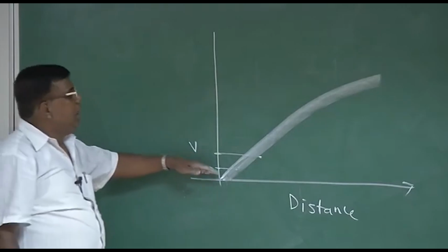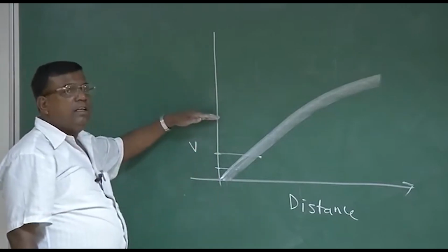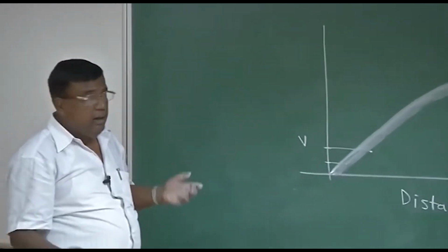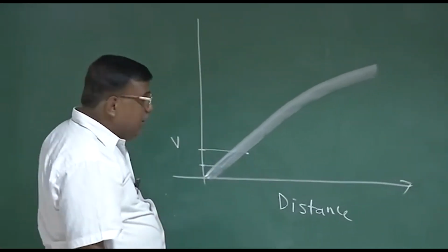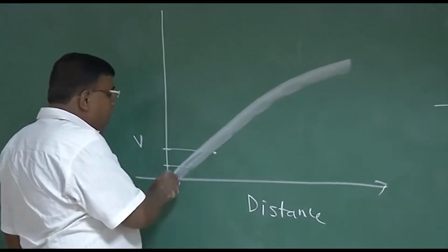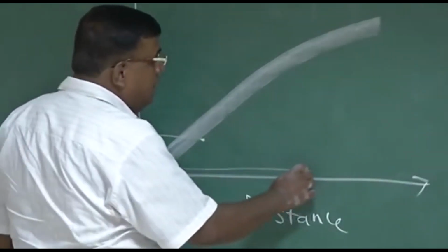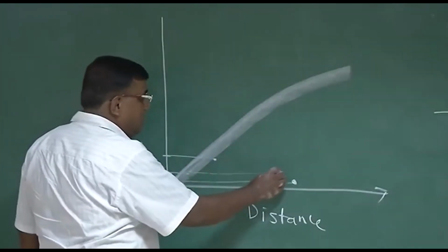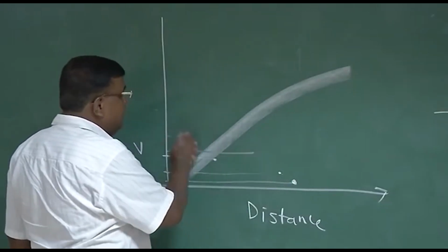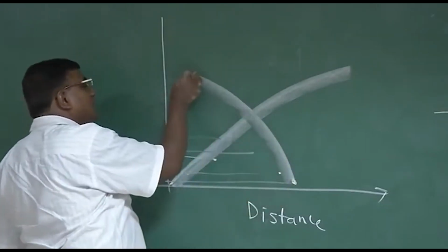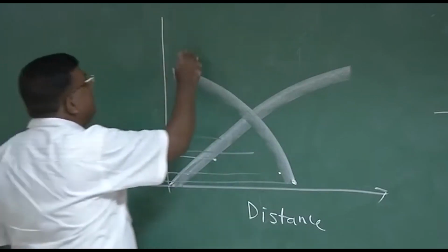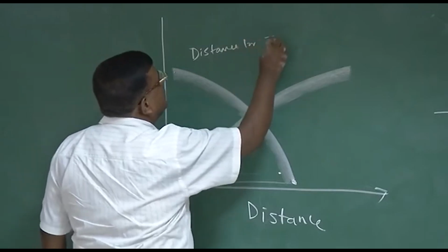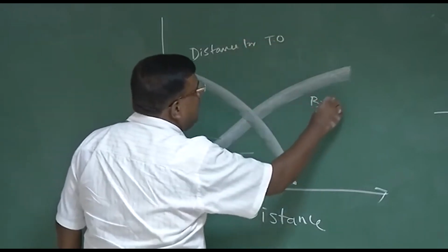I can calculate, assuming different speeds at which the engine has failed, the braking distance by using our formula SB. Now we are coming back to takeoff distance. Let us say the airplane is taking off, which has started from here, then it will take a longer distance for takeoff. At a little higher speed, a little less distance. As the speed increases, this will follow a trend something like this. This is distance for takeoff, and this is braking. We call it accelerated braking.